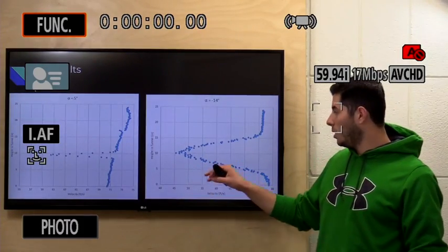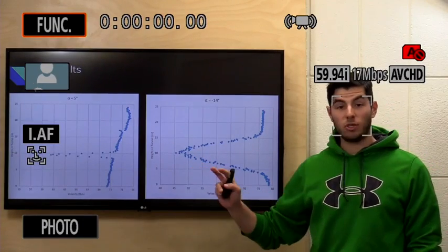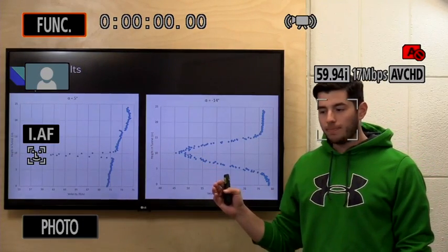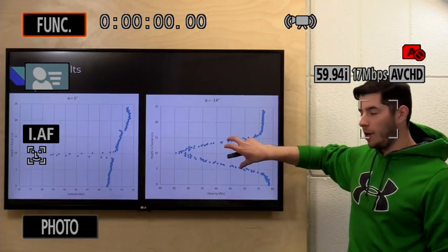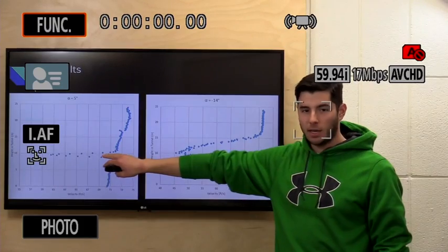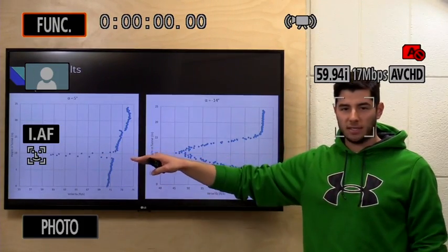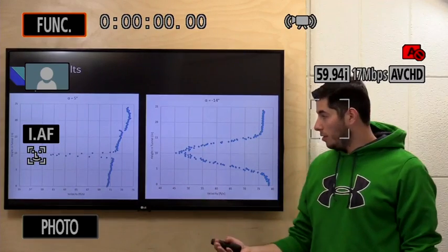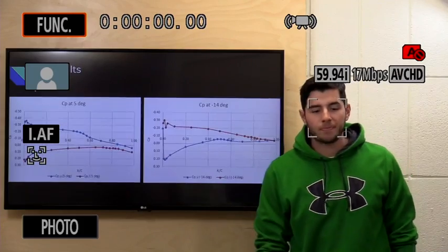As these graphs show, at a higher angle of attack, when the airfoil is essentially taking up more space within the wind tunnel, the velocity drop takes place over a larger area than it would at a lower angle of attack, because being at a lower angle of attack affects less of the velocity, therefore resulting in less of a drop downwind of the airfoil.